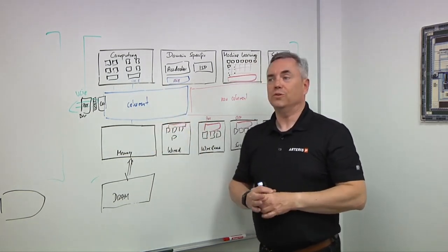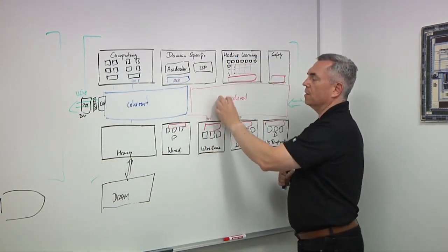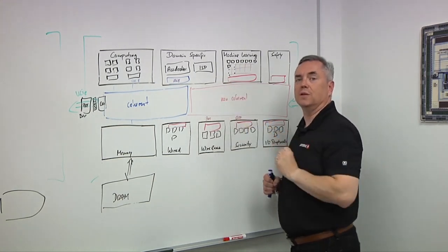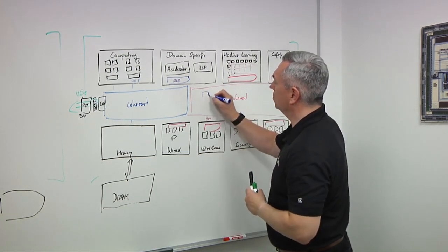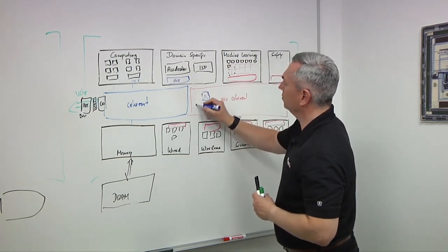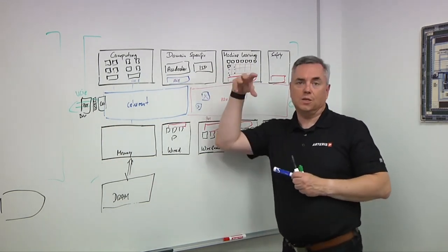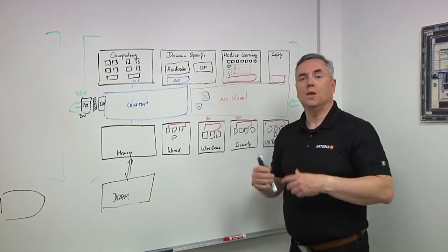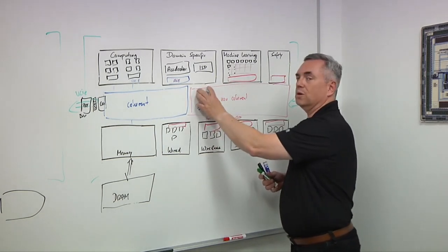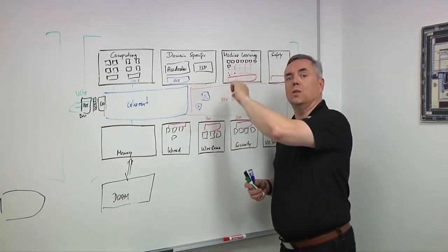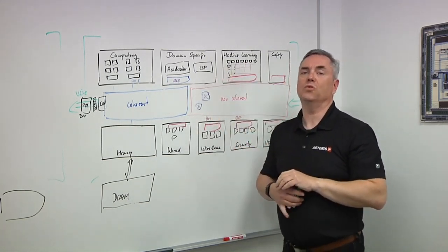Because we know, for instance, where in this coherent or non-coherent bit, let's take non-coherent, my different switches, my buffers, the different elements of the NOC are positioned. I can actually tell the layout tool, and we do this today, I have switches here and here, thinking of this more as a layout now. We give this information down into the digital implementation flow. And with that, as you pointed to thermal, you can eventually early on decide, okay, let me look at this, what type of data, how much switching is going on, what thermal effects can that have, and then be smart and move it away from some of the hotspot areas early on.